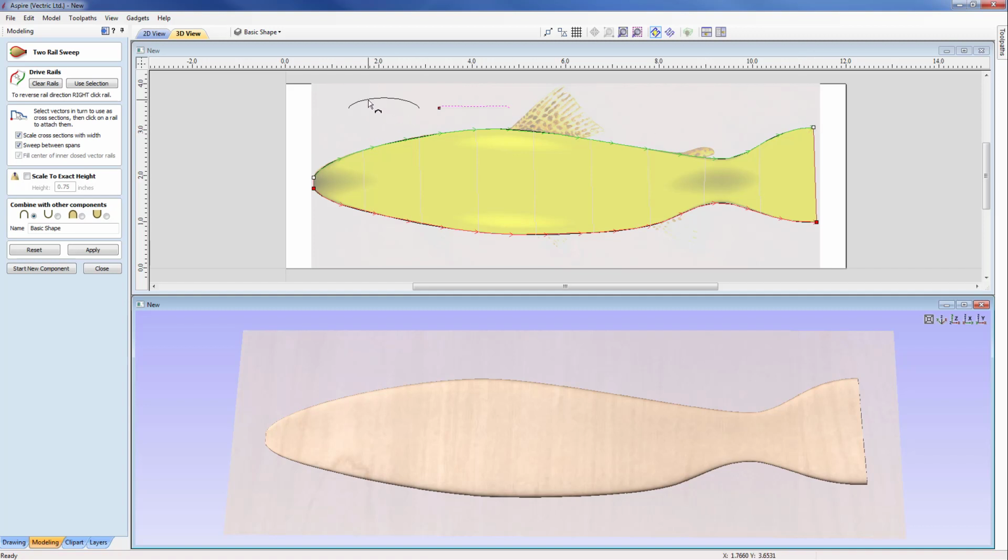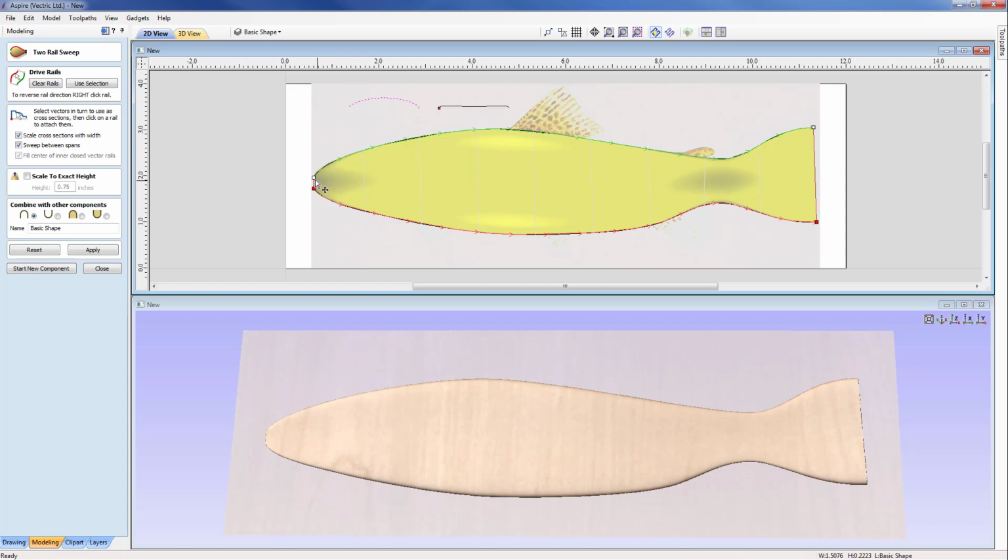We'll pick up the original contour and just make sure that we've definitely got that located on the front. We're going to transition it through and keep it rounded through to about here. Okay, we're then going to pick up the new cross section and have that transition between this profile and here, okay, roughly across the middle, and then we'll just keep it all the way to the end.